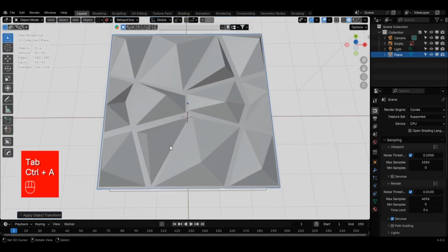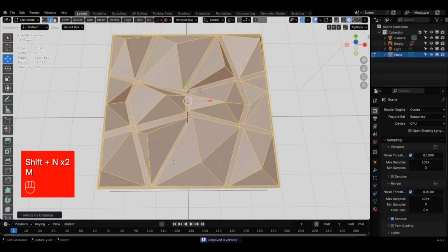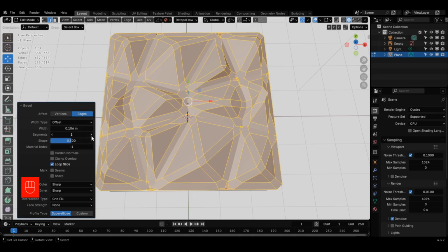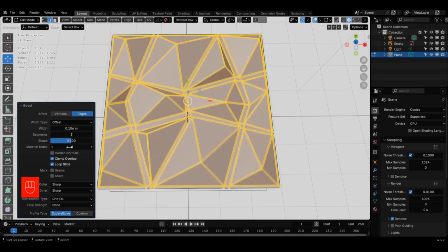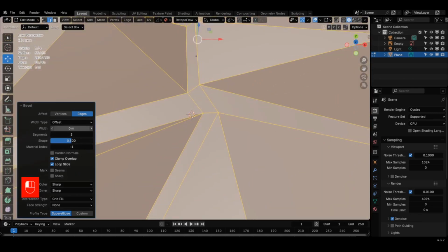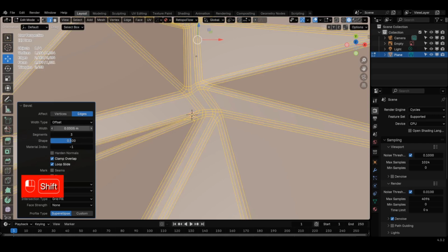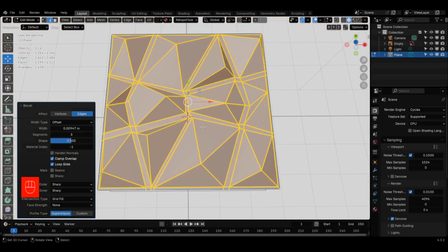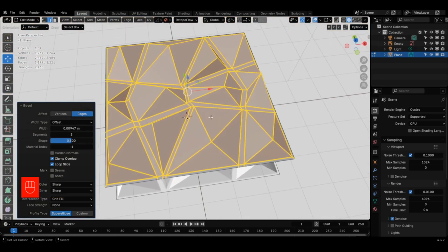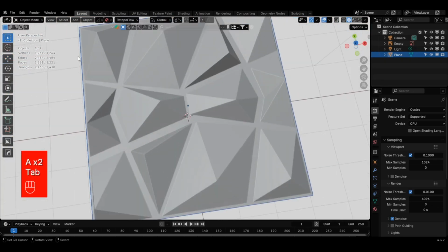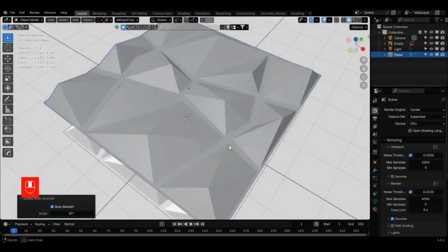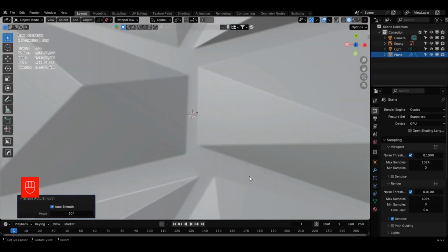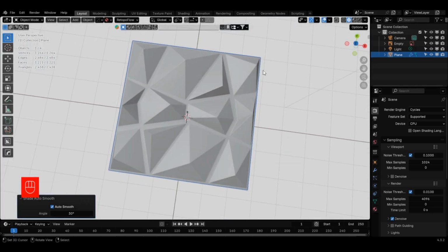And now for my favorite part, the beveling. We're going to apply a small bevel to all the edges of our panel. This step is crucial for realism because it prevents our renders from looking too sharp or digital. The bevel gives us a crisp transition, allowing the edges to properly catch the light source. These small highlights, often called catch lights or specular highlights, are what bring that final touch of realism and visual interest to the model when we set up our final scene lighting.